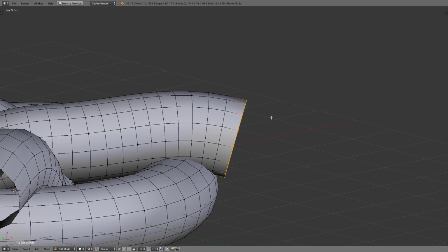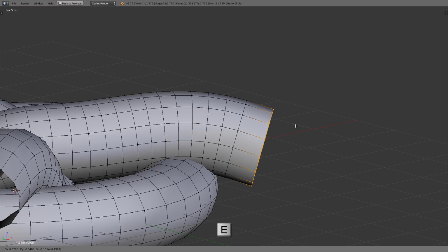We're going to extrude this to the right and then scale it down a few times until we have a nice rounded end. Now we'll extrude this the same way we did with the curves. You just simply press the E key and it extrudes it to new points and connects it to the old ones. So we'll bring this down to about right there and then left click to drop it there. And let's start scaling it down to round off the end. So I'll press S. And right now you can see it's scaling toward our 3D cursor all the way on the left there still. So let me right click to cancel that.